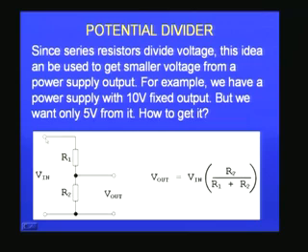You should remember that you are dividing the voltage because you want to apply a smaller voltage to a different circuit, and that circuit, for functioning, requires a current. That means the minimum current required to operate the circuit must be available from your power supply. So, I just want to show you on the screen, you have a voltage supply V in, divided by 2 resistors R1 and R2, and you apply the voltage across R2 as V out, which I take for connecting to any other device.